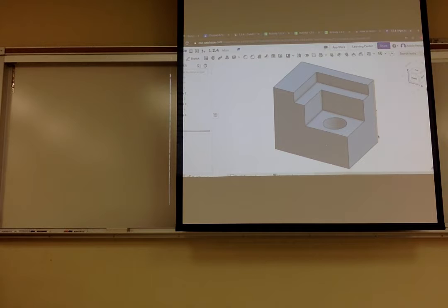So then I need to figure out how far. Because right now I've only dimensioned it so that it's 1 inch left. I can move it. My hole isn't actually located, right? So now you need to say, okay, I dimension in X direction, now I need to dimension in Y.